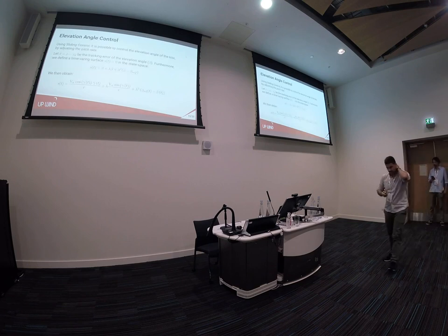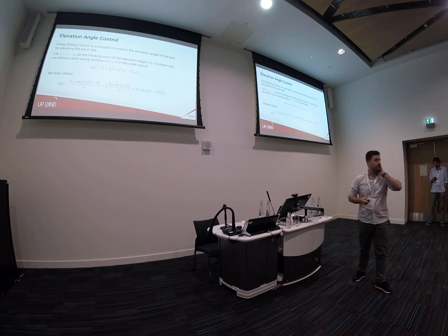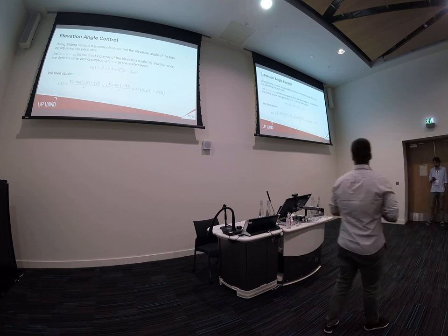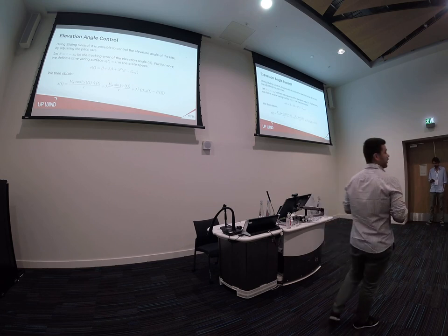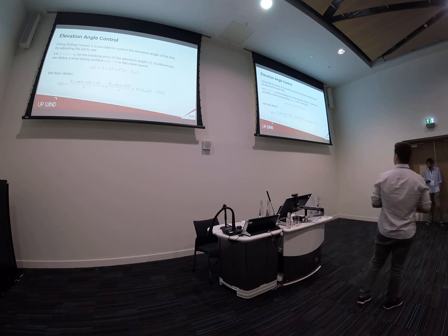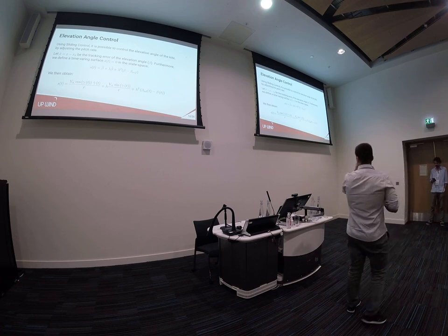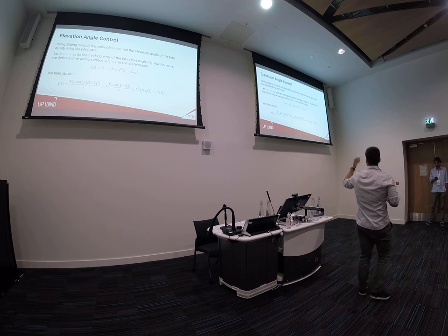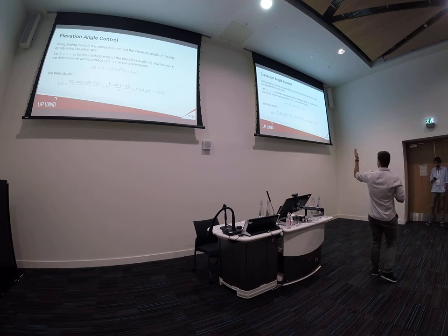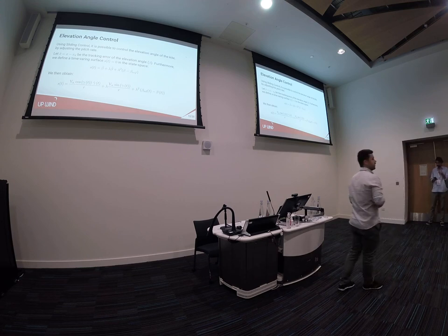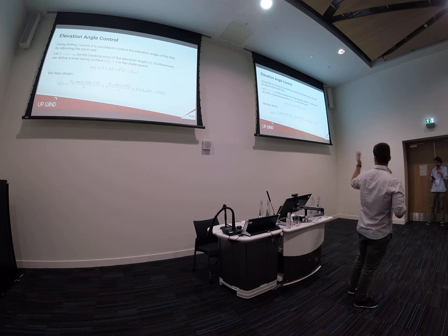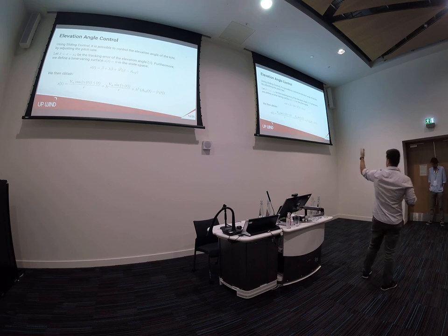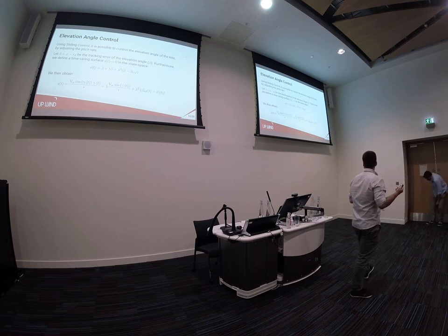And here we thought of using a sliding mode control. It is possible to control the elevation angle of the kite by adjusting the pitch rate. That's the other control variable. If we consider the tracking error of the elevation angle, we can define a time-varying surface in the state space X. And then we obtain a time-varying surface S as we show here below.